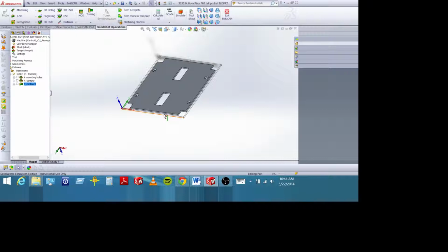So there's 20 thousandths left. You could step down by 5 more and run around, and then 5 more and run around. And then every time you're done, you could take a screwdriver or some sharp, pointy piece of metal, and push down on the floor of that aluminum. As you get very, very close, it'll start feeling like aluminum foil. It'll start giving a little bit. Okay, and then once you get to that kind of foilish feel,